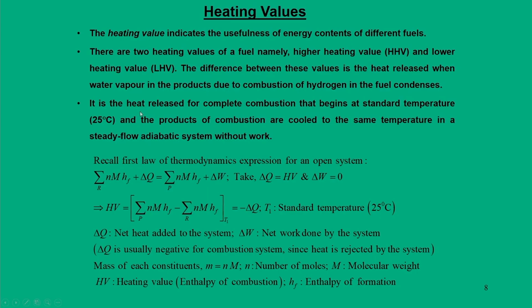Heating value is defined as the heat released for a complete combustion that begins at standard temperature, that is 25 degrees, and the products of the combustion are cooled to the same temperature in a steady adiabatic system without involving work.